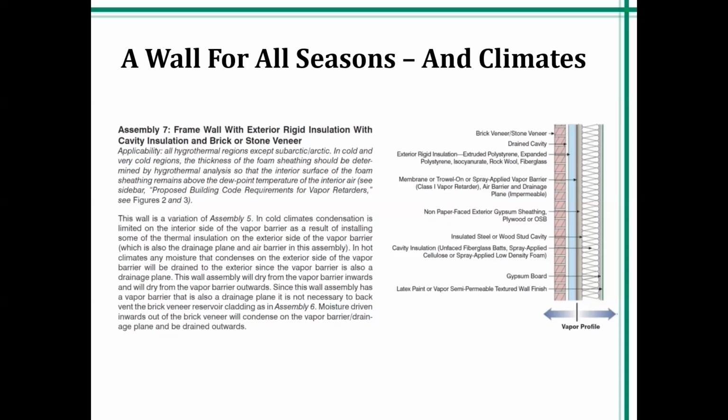When we get to 1 inch of XPS insulation, these measure out at roughly plus or minus 3 perms of water vapor permeance. So this is a permeable material. It's not until you jump to 1.5 inches or greater that you drop into a Class 2 vapor retarder. But this project team determined that they were going to specify a vapor permeable air barrier.